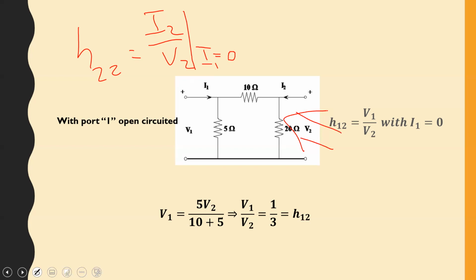The admittance. Since the first one was impedance, because V1 over I1, wouldn't it be admittance if it's I2 over V2? All right. Ms. Campbell, what's the relationship between V2 and I2? It was an accident, sir, but I would say it would be 20 in parallel with 10.